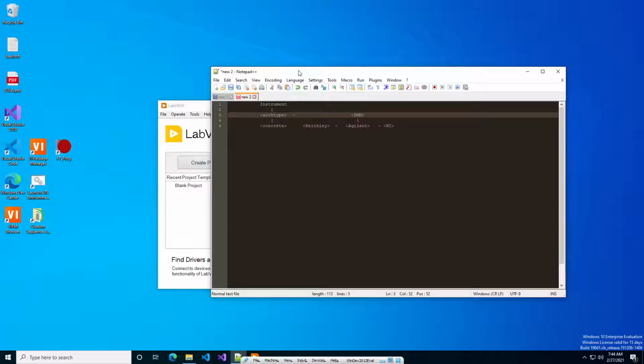So basically you have a private cluster of data that contains the data for the class. This includes your instrument handles and any LabVIEW controls or property fields that you wanted. And then it has type information that says, okay, I'm a Keithley DMM class. When you use it in LabVIEW, when you run the wire, you're running the private data over that wire.